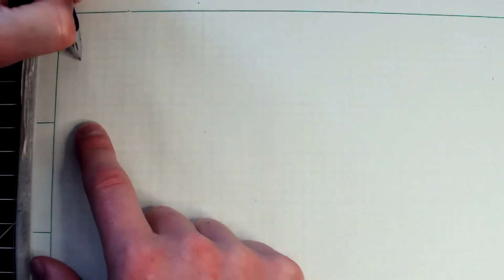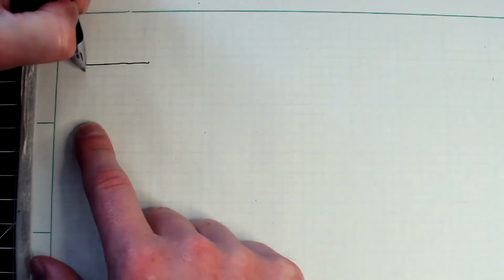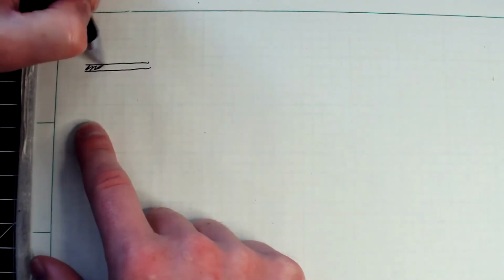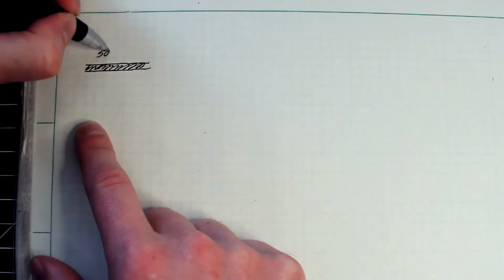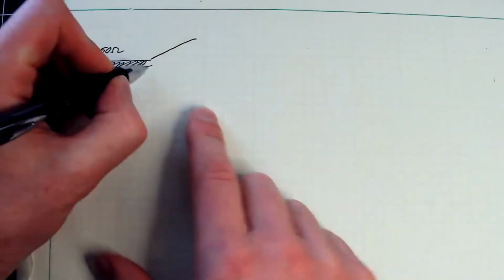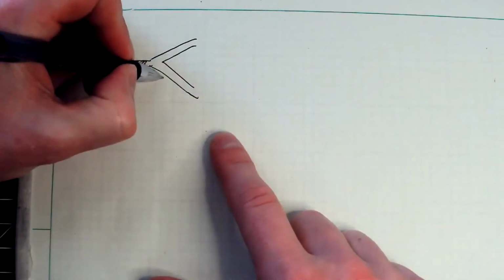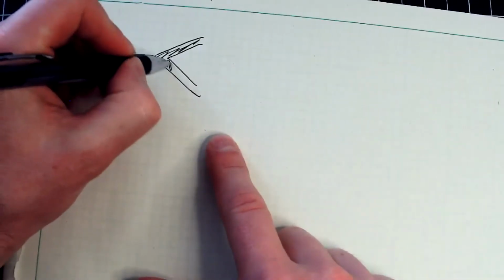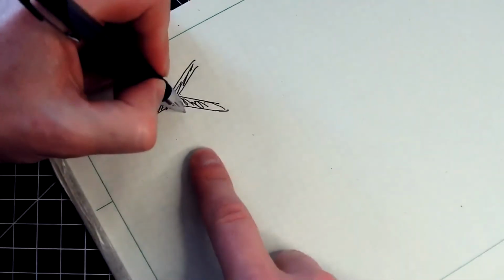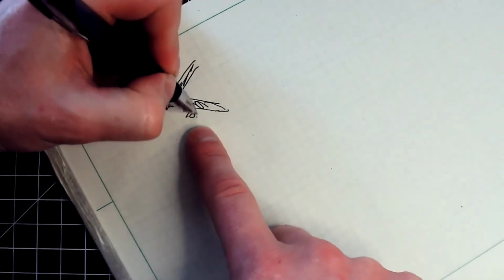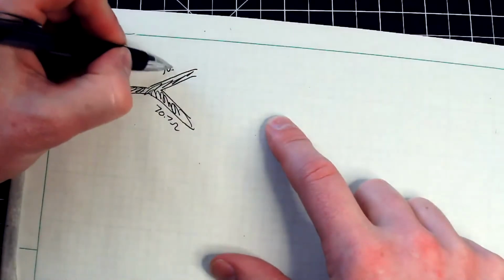So what we're going to do is calculate the frequency response. So you imagine, here is my trace coming in. So I'm going to do this from sort of a microstrip perspective. There's 50 ohms here. Sorry, let me move my screen over here so I can see what I'm doing. There we go. And this will branch off like that. And then this guy here, remember, it's going to have a characteristic impedance of 50 times square root of 2. So that's like 70.7 ohms.